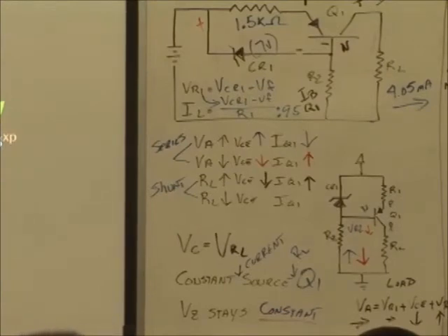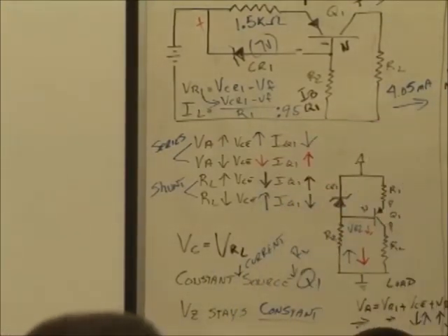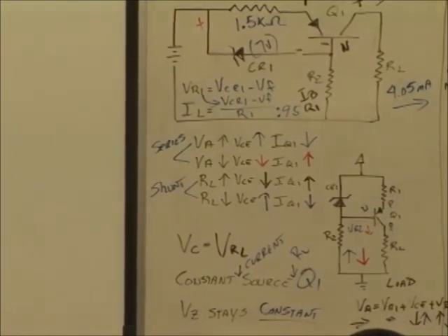The load goes down, or decreases. Load voltage decreases, VCE has to increase. So if VCE increases, it's going to conduct a little bit less. This side of the circuit, just Kirchhoff it. Bottom line, if you're not down with any of this theory that I just went over for the third time today, just memorize the arrows.